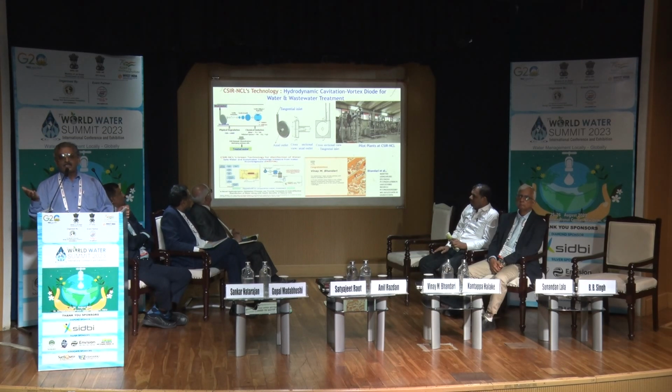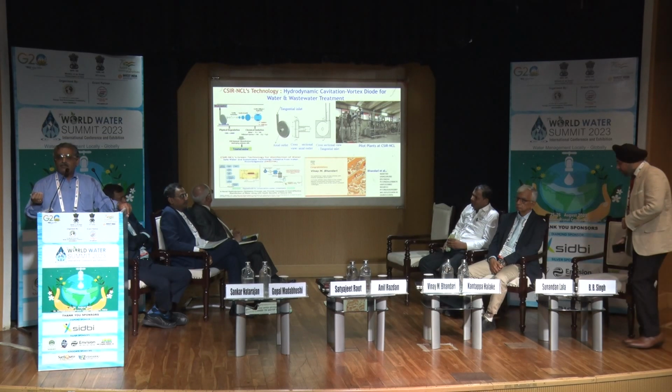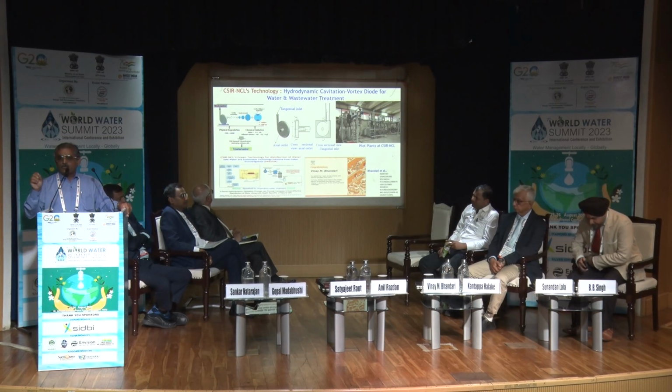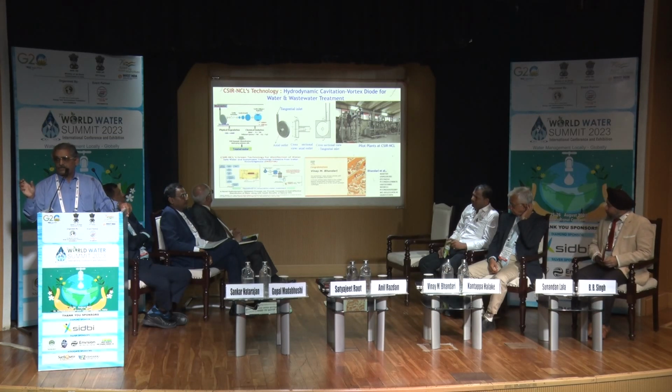Once the bubbles are generated, we allow them to collapse. This collapse is inward, so we call it implosion. It is the opposite of explosion, but it creates a similar kind of extreme conditions. Implosion creates a sudden high pressure, high temperature condition at the point of implosion, only at the point of implosion, not in the bulk. Of course, there will be some energy dissipation, and because of that some temperature and pressure rise.